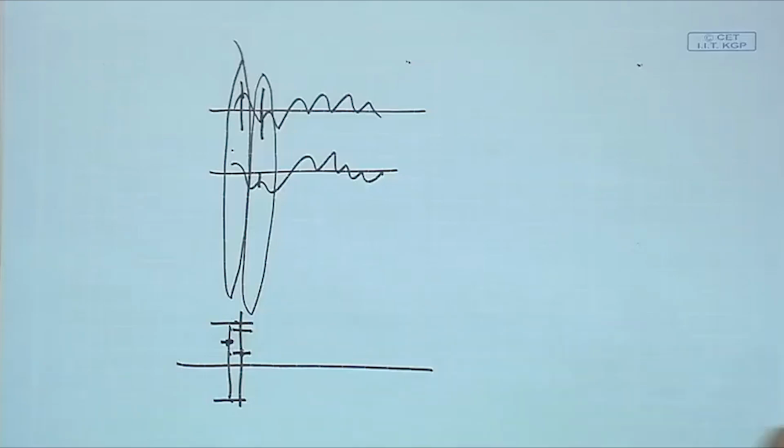So, right now you can immediately see that two things might be dependent. So, if I wish to characterize, what do I have to do? I need to go towards the joint PDF of these two random variables. A random process, I know, is an infinite collection of random variables, and there should be associated dependency among them. So, if I need to characterize the entire random process, I need to capture all those dependencies, or rather I should say the associated joint PDF of all of them.